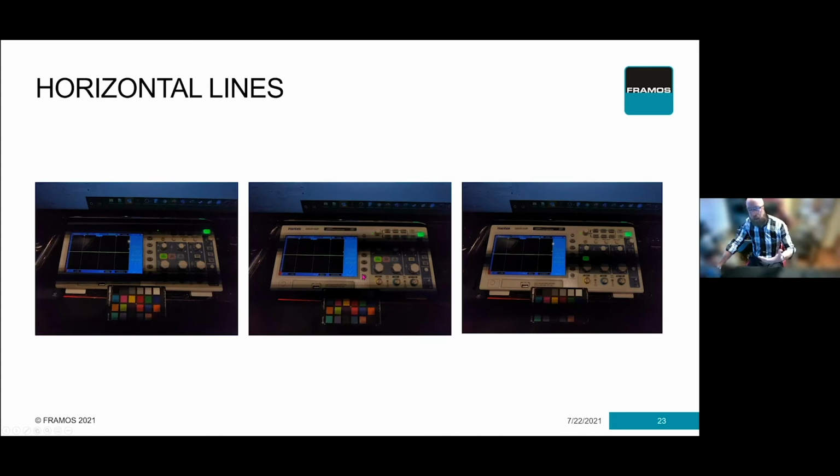In this case, I took my mobile phone, I took an image with a rolling shutter sensor, and I took an image of my oscilloscope and the old Greytag Macbeth. Unfortunately, in my office here I have LED lights that do not have any ballast. They are not DC driven, they're AC driven. So my lights flicker on and off at 100 hertz, because we're on 50 hertz power in the UK and we have a rectified signal, which means we have power twice every cycle. That means I have 100 hertz illumination flickering on and off.